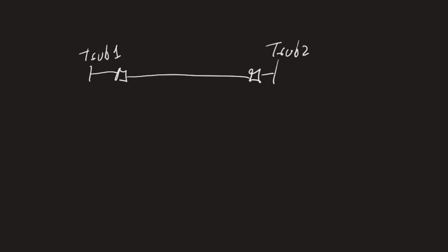To calculate the differential current, we have to add the currents on both sides of the transmission line. So in our example, let me actually go ahead and draw it over here. We had T sub 1 here on the left, and T sub 2 over here on the right. For this example, the fault was external to the transmission line at T sub 2. And we also said that the fault current was 2314 at an angle of minus 83.9 degrees. That is flowing this way.